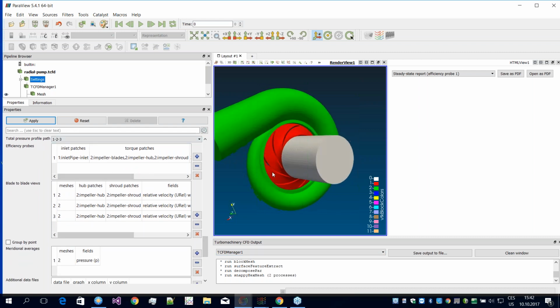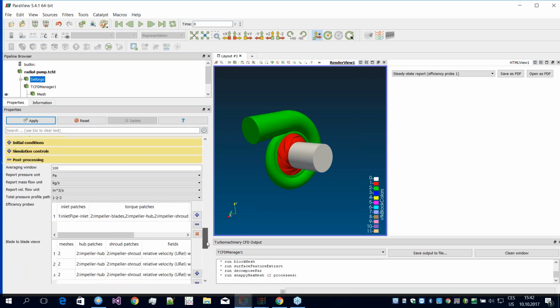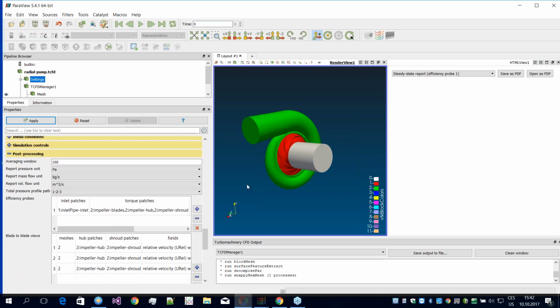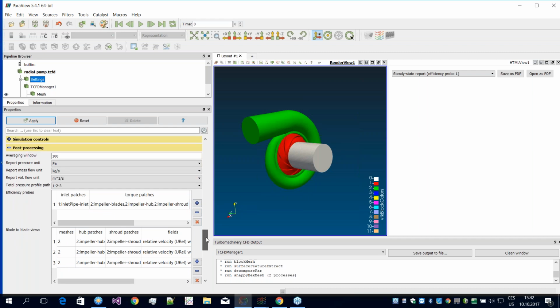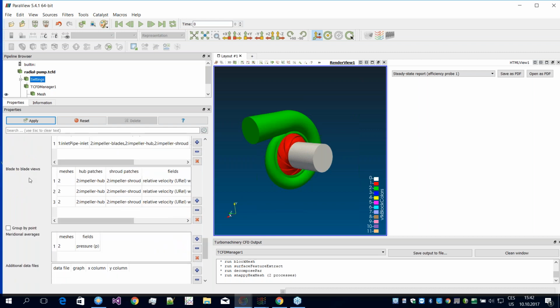Efficiency pros is nice. Usually CFD likes long inlets and outlets, but for example, you have the measurement really before the wheel and after the volute, so you can define it really here, which places are used for the efficiency, pressure drop, and other parameters evaluation.